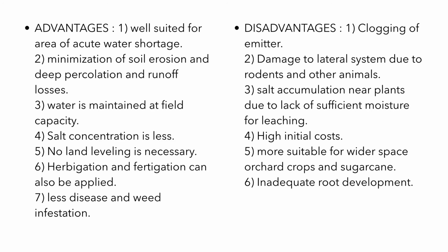The third advantage is water is maintained at field capacity. Water is provided to our field at its capacity, means there will be no wastage of water. The fourth point is salt concentration is less, so it is beneficial to our field. Fifth one is no land leveling is necessary, means we provide water directly to our plant through the emitter, so there is no need of leveling of land.